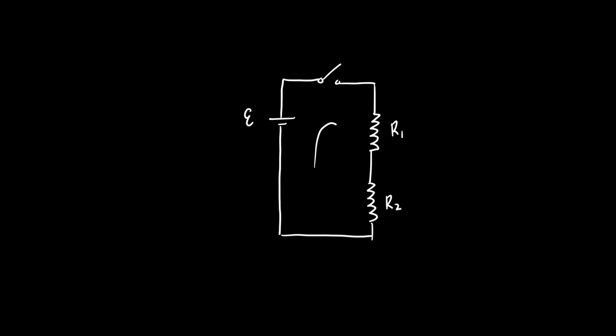So to study this circuit, we could use a single loop through the circuit. My goal right now is to develop what equivalency means for resistors, just like we did last time. Since there's only one loop through the circuit, I'll have a positive voltage because I'm going from the bottom plate to the top plate of my EMF. I will then have a voltage drop across resistor 1, and a voltage drop across resistor 2, and that has to equal 0.